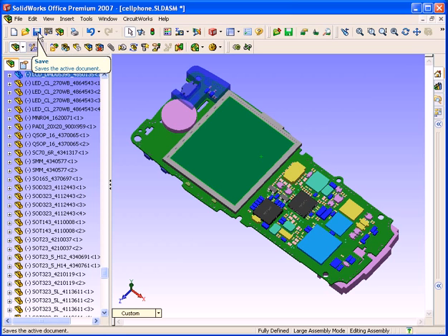So now, for example, if I was to export this SolidWorks assembly back out using CircuitWorks as an IDF file, that updated custom property information, that updated reference designator, would go across into the IDF file and obviously back into the ECAD system. So changes made to the reference designators in SolidWorks can be taken all the way through and back into an ECAD system.